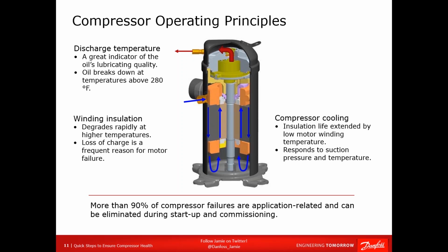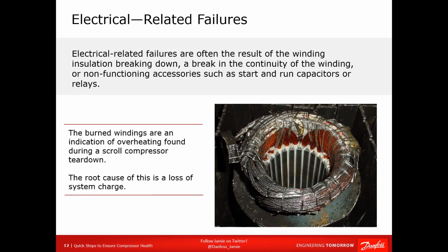So, rule number one is when you have a failed compressor, and I say 90%, it's probably closer to 99% of compressor failures are application related. And these can be eliminated during startup and commissioning and during preventative maintenance. So you want to keep that compressor cool and dry and good lubrication going on inside.